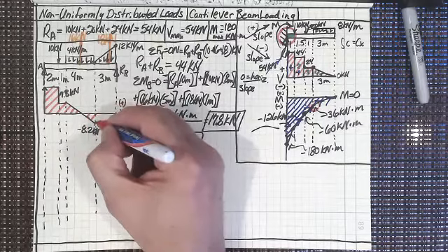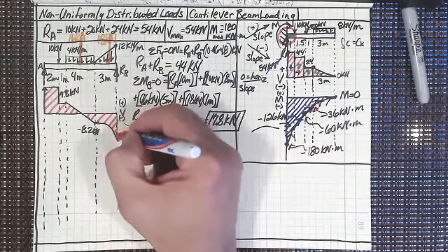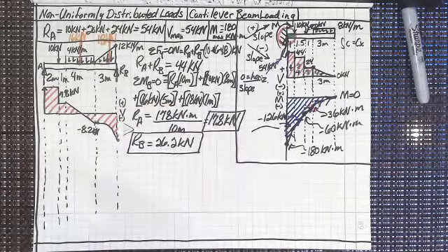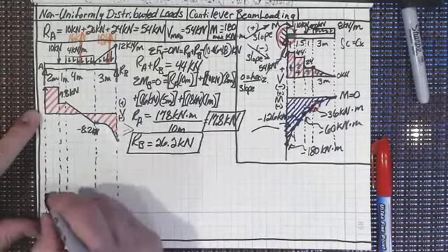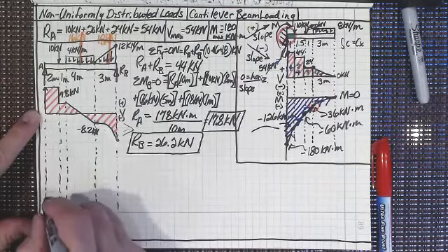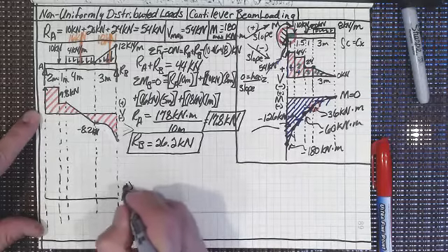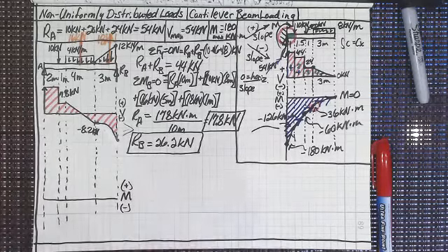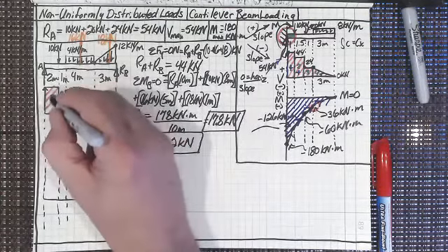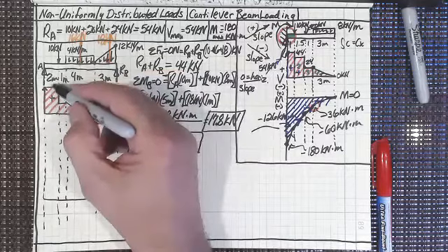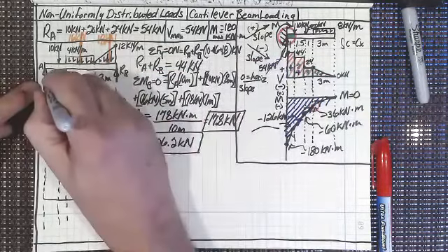And I think you can see how I'm going to find out what the maximum is there, right? That's right. Because you can see that on the left-hand side of this, I'll just call this my bending moment diagram down here and give you as much room as possible to see it. Okay, so first of all, it's positive. That's positive, and we know what that value is. That value is 17.8.